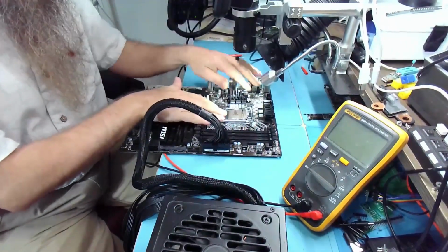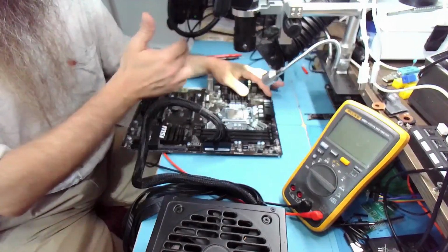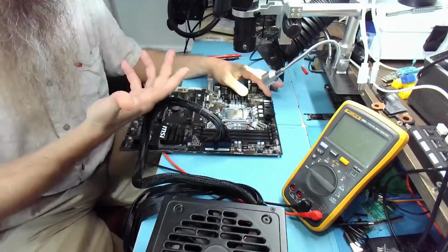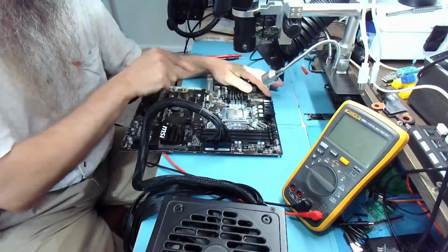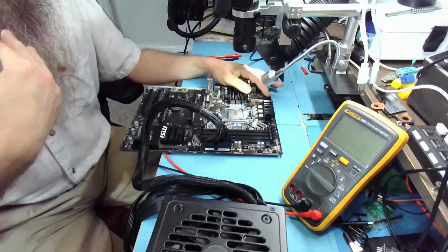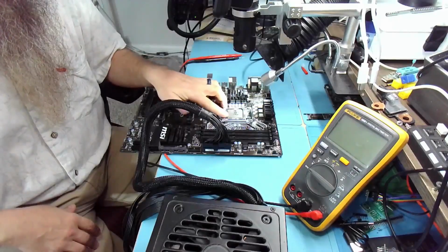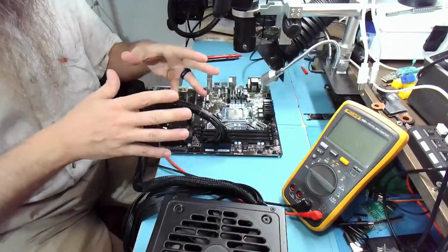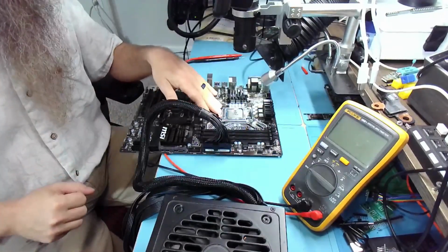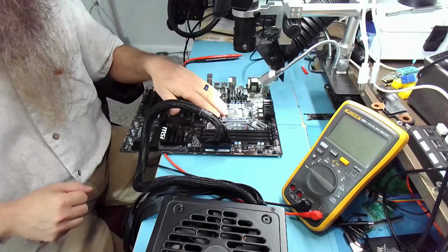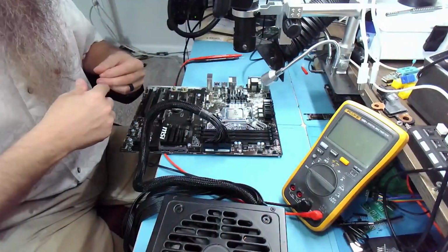Remember when I connected 12 volts to the VCore and the high transistor was shorted, which means that 12 volts went through the coil directly to the CPU, to the VIO. So I'm thinking if the VIO is shorted here on the CPU, and unfortunately I can't confirm that right now because I'm still waiting for replacement CPUs, that would explain why the other board turns on and turns off.